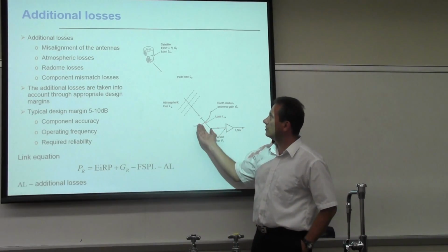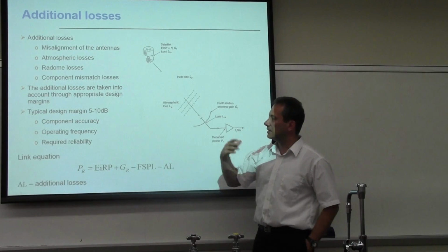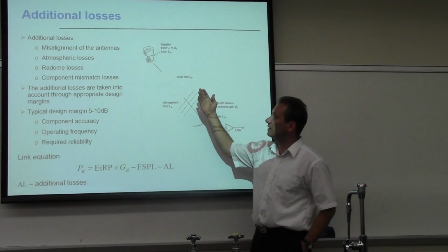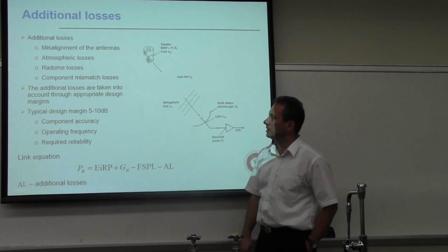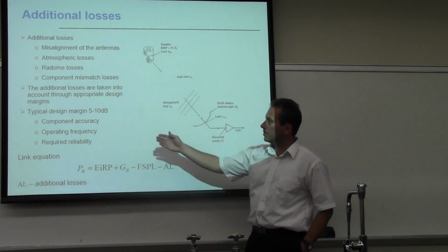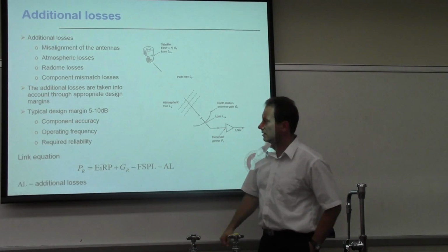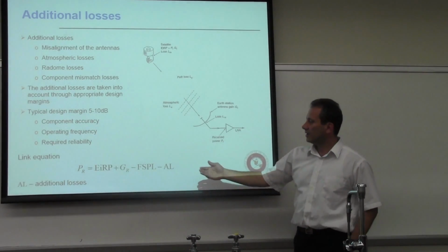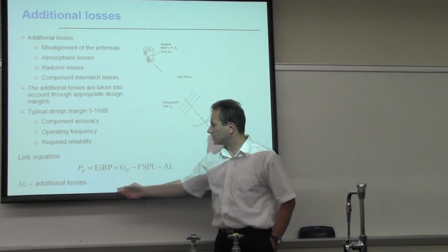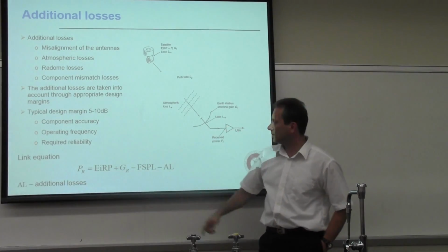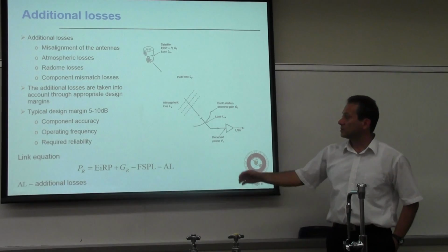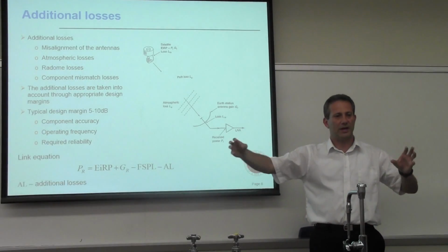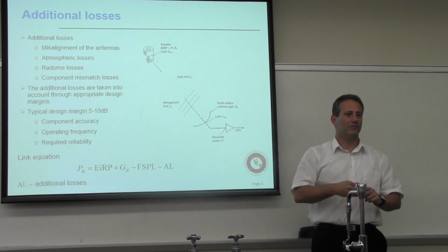So that means that you are routinely transmitting slightly 5 to 10 dB more power than what is required to maintain the link, but then when something happens, you're still keeping the link on. And this depends on all of these components that we have here. So in general, we have our receive power as a function of what you transmit, your receive antenna, free space loss, and additional losses. What I'm trying to do is decompose all of these gains and losses into link budget items.